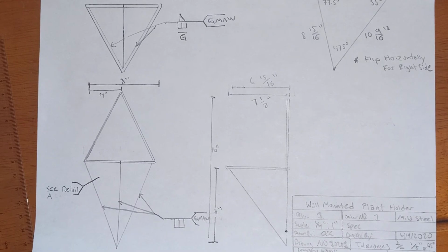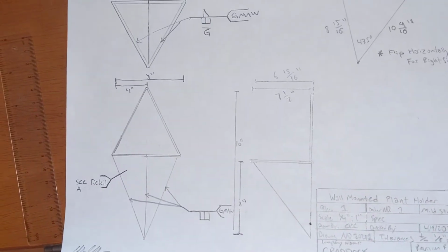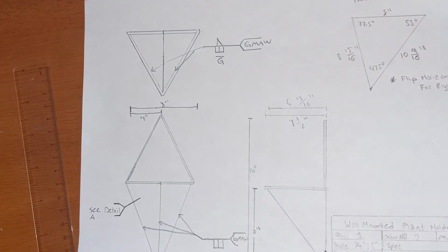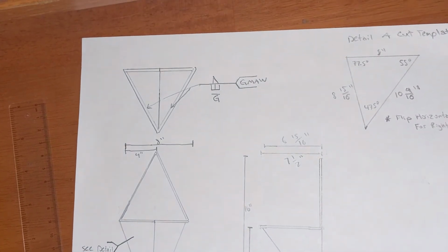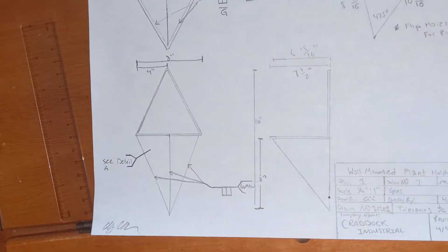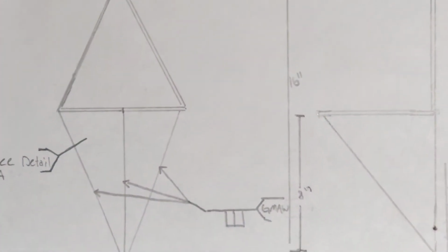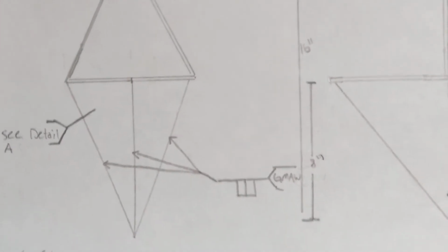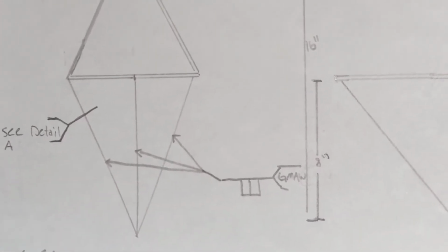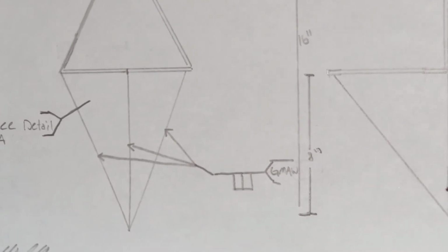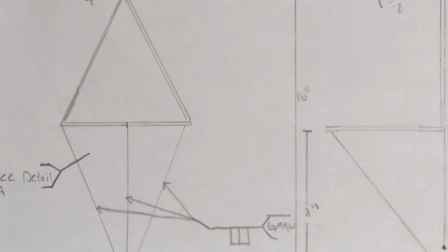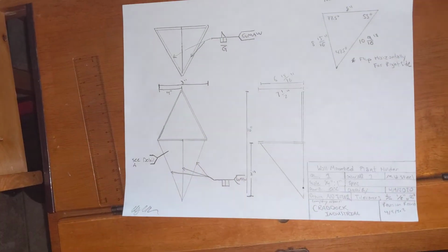So we have our front view down here and our top view that also has a very important part of your project blueprint, which is our weld symbol. Okay, so down here in the bottom, you see I have an arrow drawn with, on the arrow side, an edge weld call out. And I even put a specific note saying that I did this with GMAW. So I did all of my welding here with a little MIG welder up at campus yesterday.